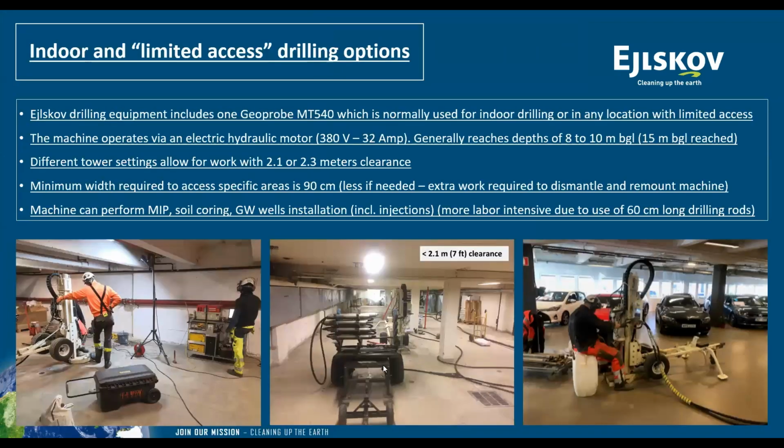A little touch on the mini rig so that you can see what we are talking about. So we have been doing MIP investigation, wells installation, soil coring, and also injections within confined spaces, being basements, being offices, being in this case, car dealer active shops. And what these machines allow us is to really fill in some of the critical data gaps when it comes to some of the active sites that you may find anywhere. So it was just a few pictures to show that sort of feature.